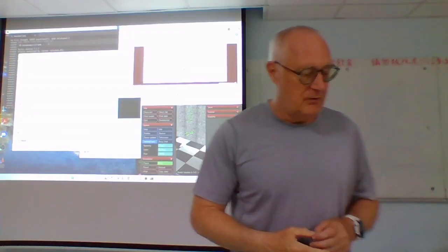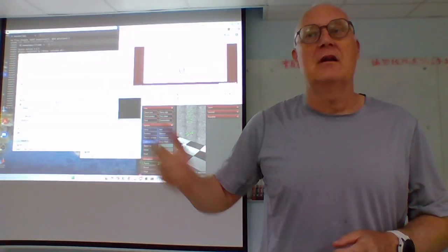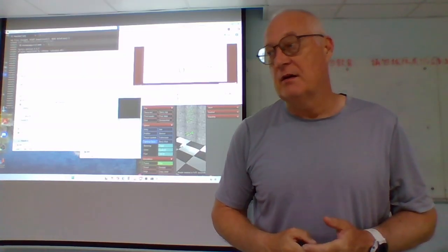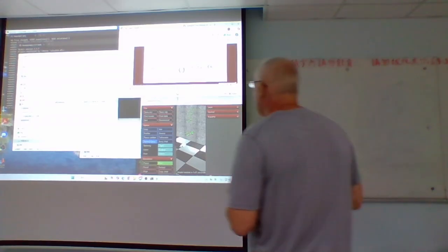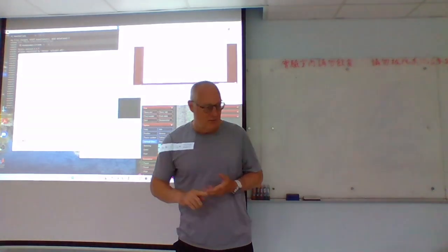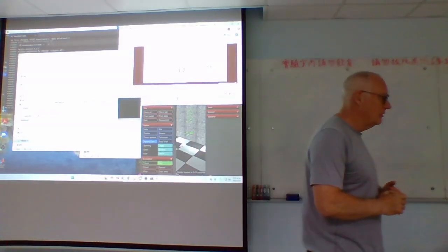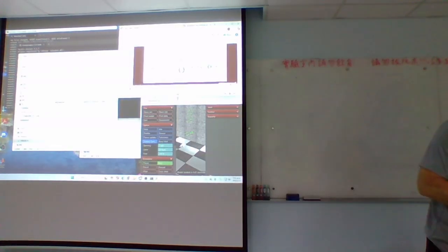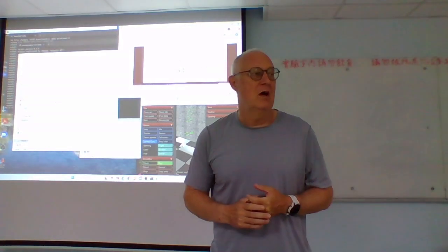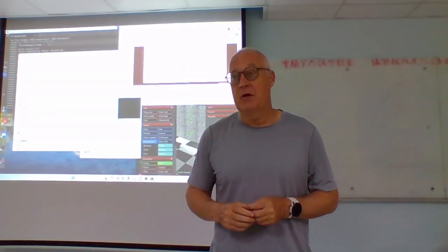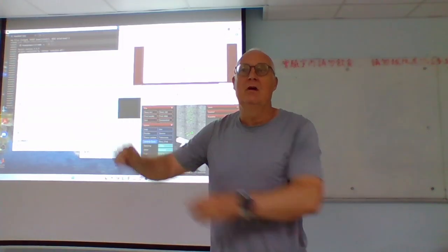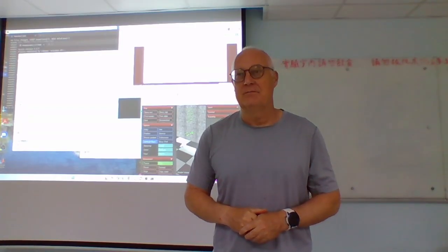And if we have a displacement, a linear motor, then it would be a translation. That is what is changed by the joint. Now we have that. We now need to figure out what these transformation matrices are. Once we have those, then we can at least solve the forward kinematics problem. Right? Then I can set joint configurations, and then I can figure out what's the world coordinate of the end effector.